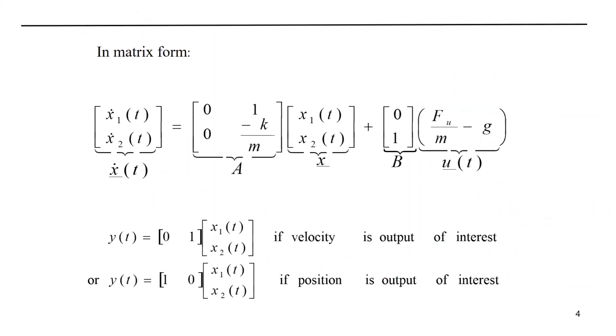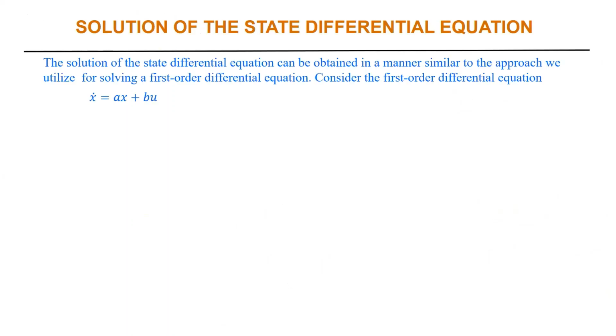As I said, we will come later on and discuss, in general, if you have a differential equation or a transfer function, how you can get the state space representation. But now, let me move into the solution of the differential equation. I have x dot equal Ax plus Bu, y equal to Cx plus Du. The problem is in solving the differential equation, because the other one is an algebraic equation. If you solve x, just substitute in the second equation and you will be done.